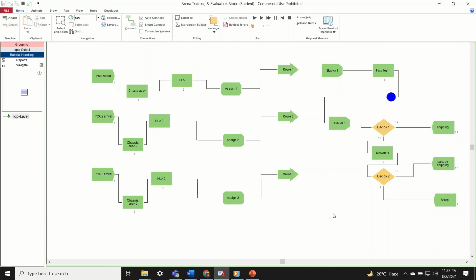That is where we get R&D attention, or the ER, as we call them, the engineering responsible person, to look into this and make sure the test sequences and test algorithms are able to cope, putting in some interceptions before the final test one, and making sure that before it goes into the final calibration and verification process, it has a matching compensation to the components so there is no matching issue at the final test, which is causing about a 50% first pass yield loss.